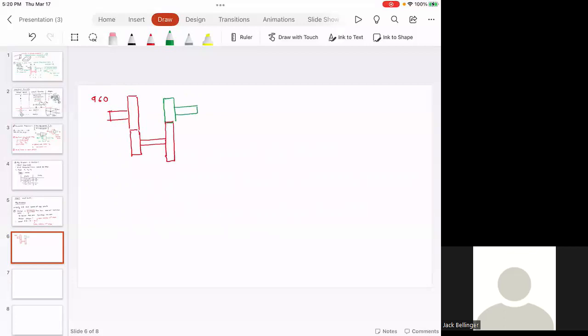How would the power flow? This will rotate this gear, gear 1 would rotate pinion 1. Pinion 1 would be attached to gear 2, and then this will be attached to pinion 2, and this would be the output shaft.